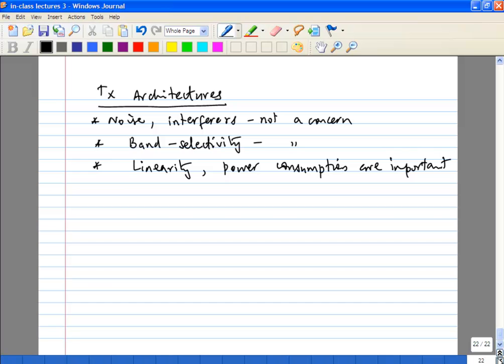You can see the dynamic range difference. So you are far above your SNR requirement. Your SNR requirement may only be from your digital baseband, maybe like 10 or 15 dB, maybe 20 dB maximum. So you will be much higher than that. And remember you are actually transmitting into a background of noise, right? As long as you transmit high enough power, that won't be a problem.